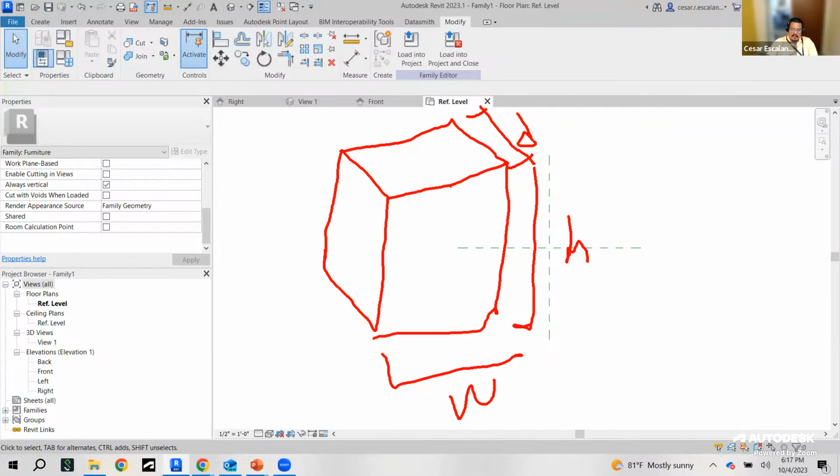Then I need to add a door that in projection has a swing representation, and maybe two handles. And then this wall cabinet needs to be able to generate different family types assigned to the different parameter values. So I can have a 36 cabinet, 24, 18, etc.